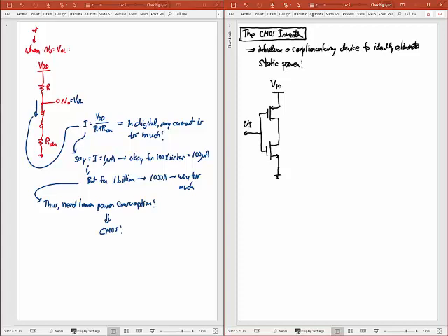There's V sub I. And in order to avoid threshold change effects, normally what you do is you just tie your source for the PMOS and the NMOS to their bulks. That immediately eliminates all those complications due to threshold effects. I'll call this MP for my PMOS device. I'll call this MN for my NMOS device. And my output will be the same. Have an output voltage, and basically the next stage is going to be capacitive.